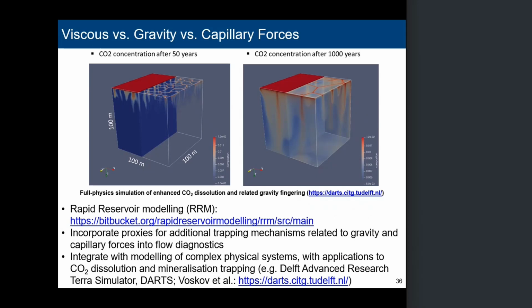So in terms of CO2 injection, that is in general not the plan. You might use an off-take well, say in a depleted oil and gas field where you're worried about pressure building up against sealing faults. You might need to bleed off some of the pressure to allow more pore space to get more CO2 in. So that probably will be the case in some applications. But say, a big saline aquifer, you wouldn't want any off-take wells. You basically just want a handful of injector wells, widely spaced, and then you would let the pressure dissipate away from those. So the setup on here is kind of artificial, but we can now do some more sophisticated things in terms of well placements, a bit closer to what will happen in reality.